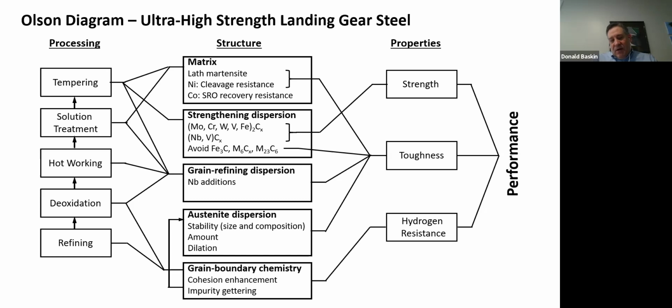This is where you have a material that is a high strength material. Typically, it has a yield strength over 1 gigapascal. And what happens is when you, for example, electroplate this material, a little bit of hydrogen diffuses in, because you're oftentimes, or most of the time, dealing with an aqueous solution. Electricity during the process turns the water in the plating solution to hydrogen and OH. The hydrogen diffuses into the material. It begins to accumulate at grain boundaries and then creates pressure until the material cracks without warning.